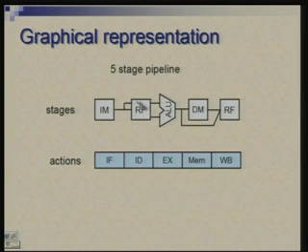You are reading here and you are writing here. So, it is the same register file, but logically I want to lay it out, conceptually showing it as a linear pipeline, or I can show it in terms of actions, that the action happening here is instruction fetch, instruction decode, execute, memory access and write back.